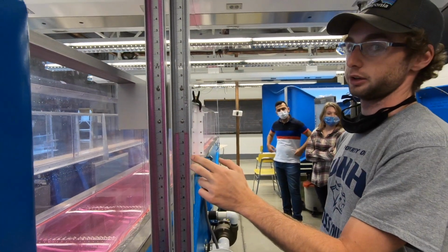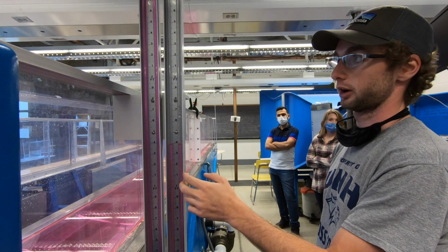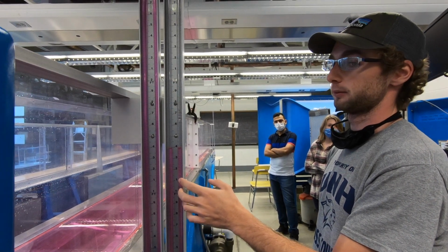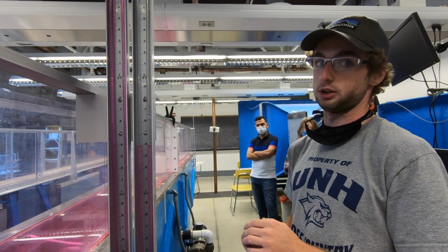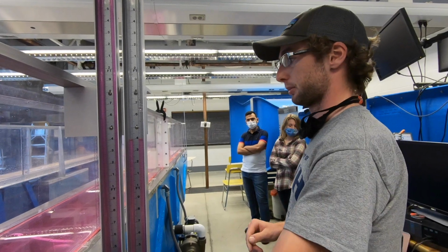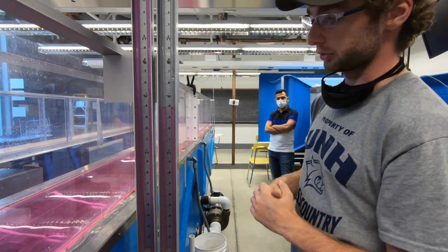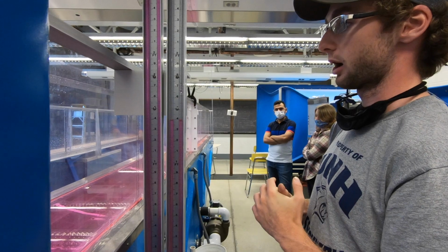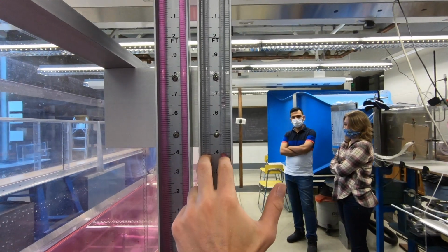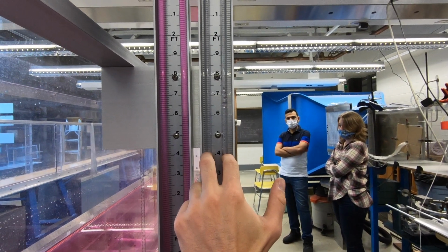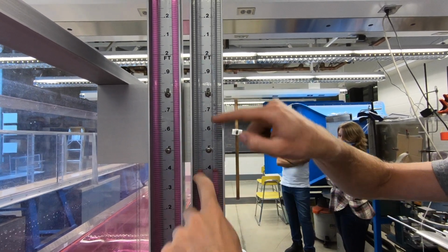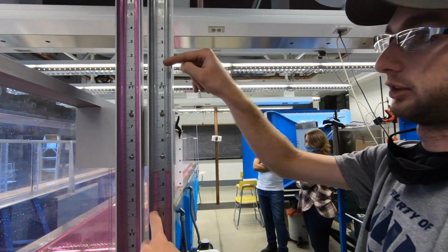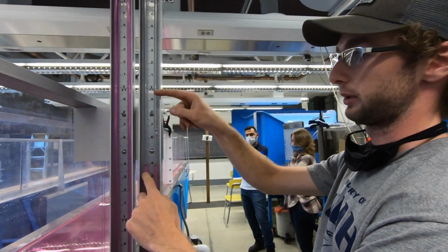These are going to read the height of the velocity of the water coming through the pump orifices. So there's a large orifice and a small orifice, which are essentially the valves that the water flows through from the pump into our tank. The deflection of the manometers is read by taking the difference in the level of these two columns of water. So if these two columns of water settle 1 foot apart, our deflection would be 1 foot. If they settle 1/2 foot apart, our deflection would be 1/2 foot.